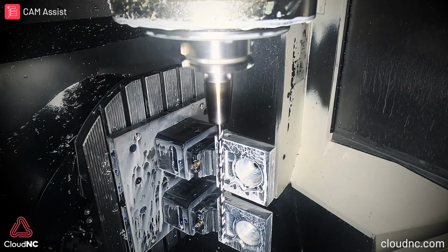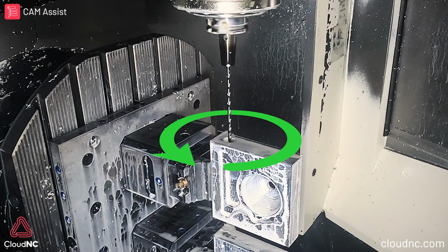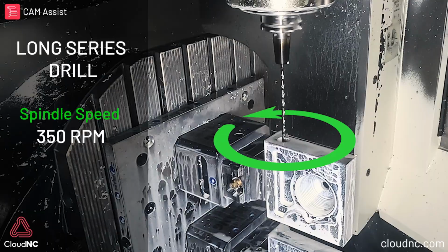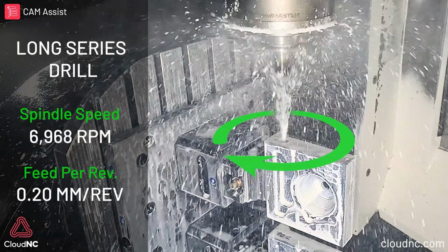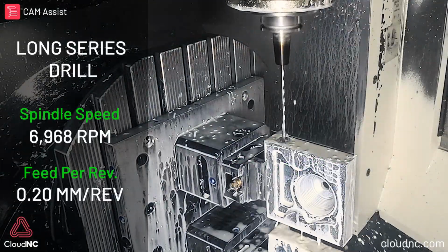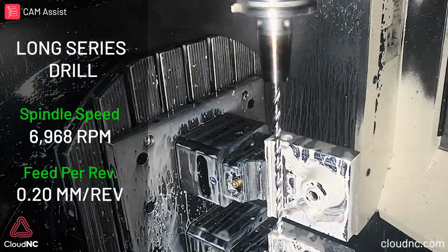As the long series drill enters the pilot hole, an M04 command must be used to rotate anti-clockwise. This is to ensure the cutting edge does not snag on the edge of the pilot hole on entry. Once the long series drill is submerged into the pilot hole, the spindle then stops, before spinning up clockwise to full RPM. Through coolant then comes on, and the drill feeds straight through the material. The spindle speed is 6,968 RPM with a feed per revolution of 0.2 millimeters.